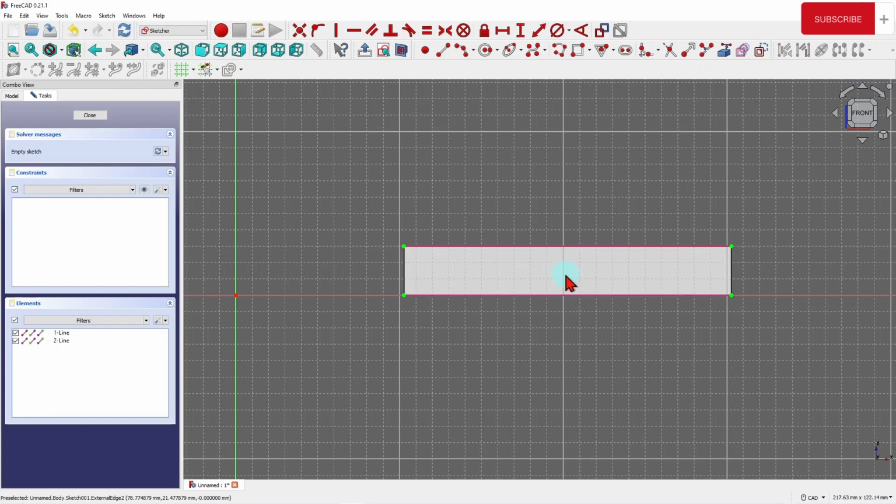They are designed on the sketch, and they are going to be helpful for me to start creating geometry on this face. So the first thing we're going to do is put an arbitrary node or point here, which is a construction point, and I'm going to try to make it the center here. Now I got at least that point to lie on the center of this line. Then I want to find the center in between these two. I can do the same, put an arbitrary point here. Right click to get out of here, and use the symmetry option.